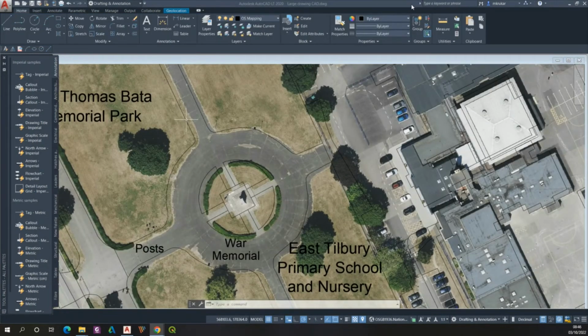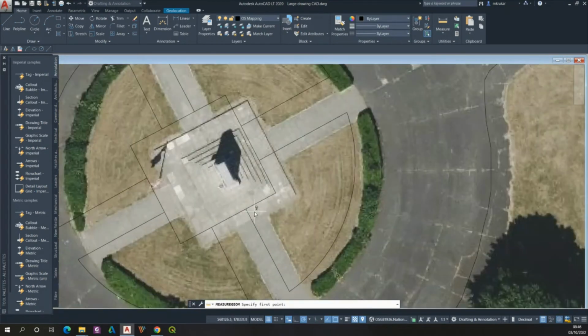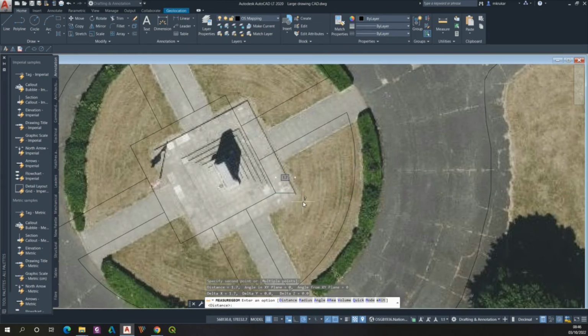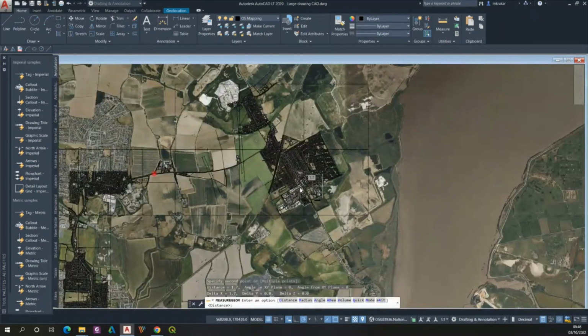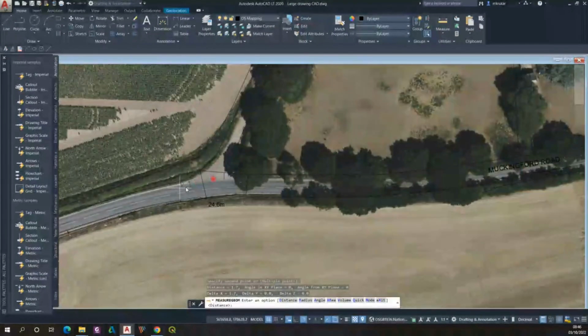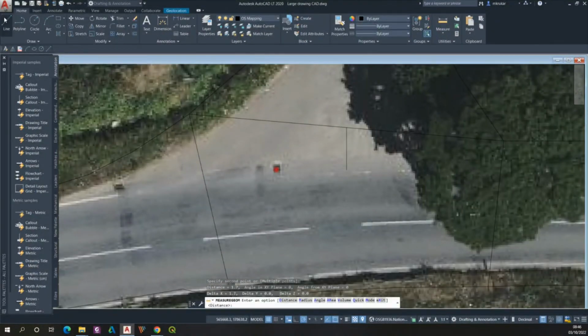And now I can go back to my previous step, discussed measurement, distance, and measure the distance optionally between this corner and the corner represented on the map. Let's assume that this is the same line, and I have 1.7 meters of the shift. So what does it mean? In my point here, I need to draw the line in the opposite direction, which counts 1.7 meters here, right?